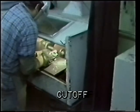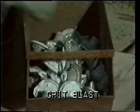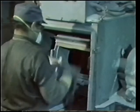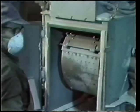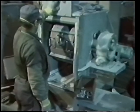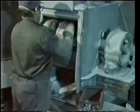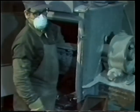The part now undergoes a variety of finishing and inspection operations. The parts are separated and the sprues and runners cut off. Excess molding is removed by an automatic tumble blast operation. Here, small sand-like particles of aluminum oxide are placed in a barrel along with the parts. When the barrel is rotated, the particles abrade the part surfaces, mechanically removing the molding material. This operation can also be done with various other sand or grit blasting techniques, depending on the design of the part.